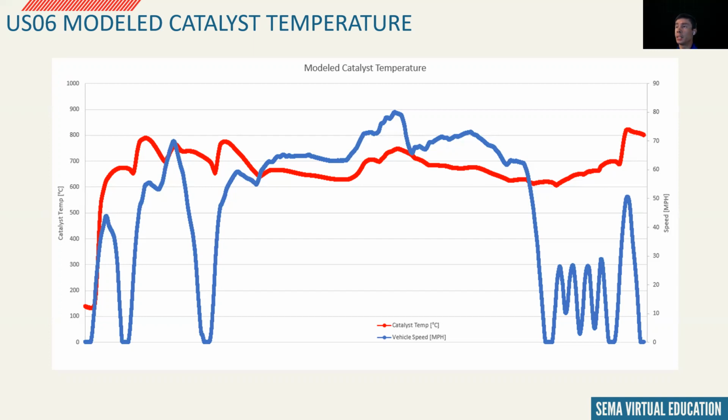If the model temp is higher than actual, COT will be too active. This will cause high CO and high hydrocarbons, for example. Lower than actual, catalyst damage will occur. If damage occurs, this will also affect the emissions. We need to take care of emissions components or after treatment durability. This will also cause reliability issues and warranty claims.